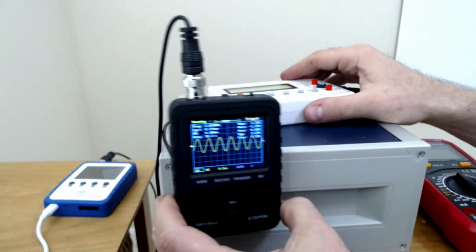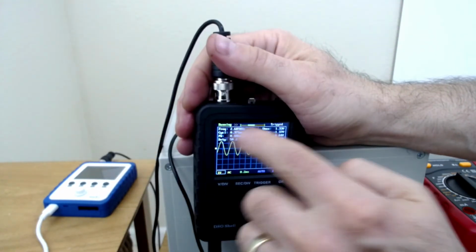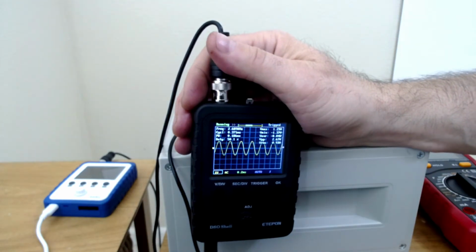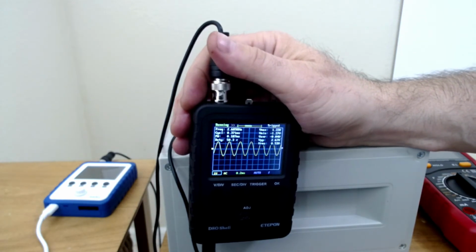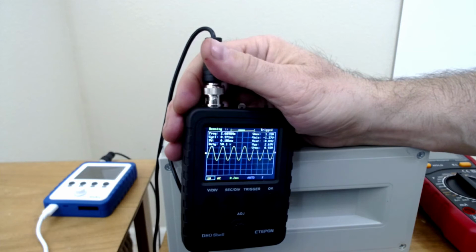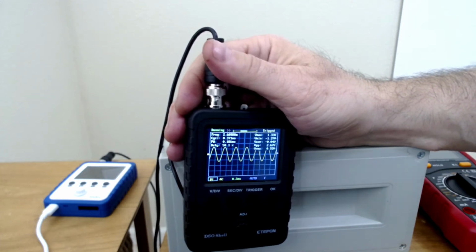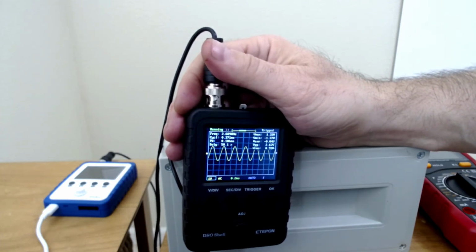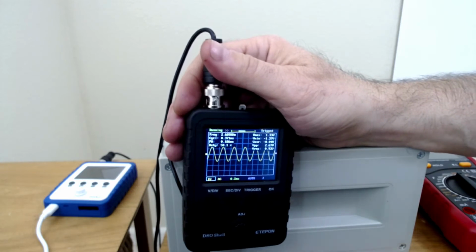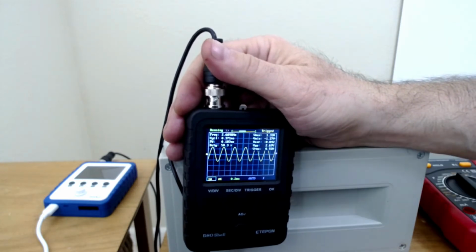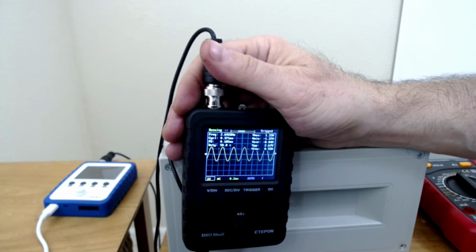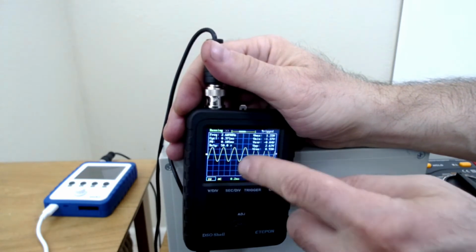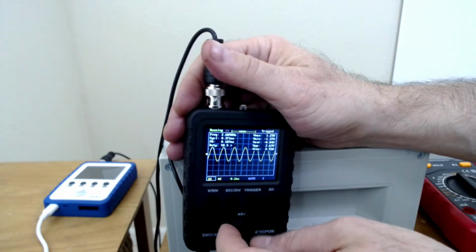Now this scope does display a lot of stuff on here. You can use it as a check, but I want you to measure things, because I don't know how accurate some of that stuff is. In the earlier class, I had the signal generator set to 1600 hertz, and it was measuring 1700 hertz. I would actually go by measuring the signal on here.